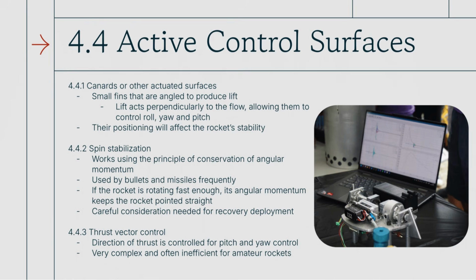And then lastly, thrust vector control. Very difficult, very complex to do, but arguably one of the best ways of controlling your vehicle. You can control it based on either some sort of gas injection into the nozzle, or gimbaling, or mechanical systems to control the thrust vector of your engine.